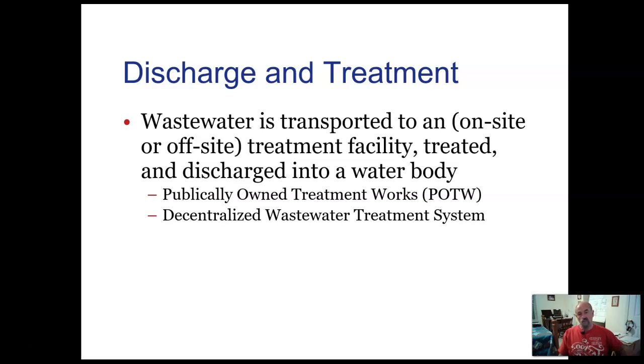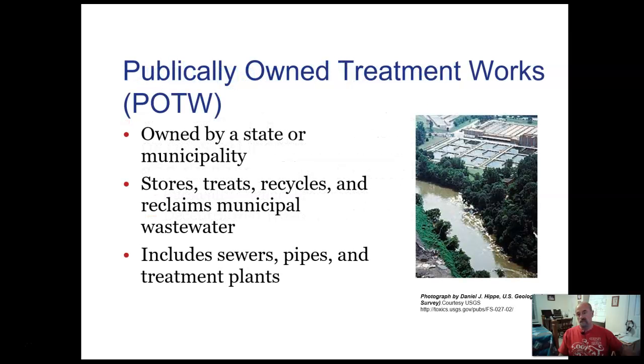Discharge and treatment. Wastewater is transported to an on-site or off-site treatment facility, treated, then discharged into a body of water. Publicly owned treatment works, POTWs, or decentralized wastewater treatment systems. Those are the two we'll talk about. A publicly owned treatment works, owned by a state or a municipality, stores, treats, recycles, and reclaims municipal wastewater. They're talking about a city sewer system. It includes sewers, pipes, and treatment plants. The picture they're showing there is of a facility near Atlanta, Georgia.